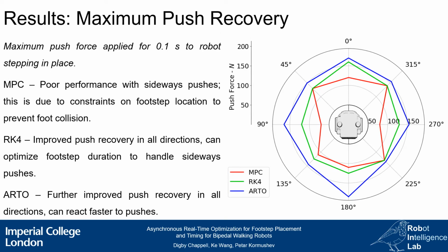The maximum push force for RTO was considerably higher than for RK4 and MPC in all directions. Particularly important is the improvement over MPC in the sideways directions, where step location is constrained to prevent foot collision, so step duration optimization is favourable. RTO is able to react more quickly to the pushes, giving improved performance over RK4.